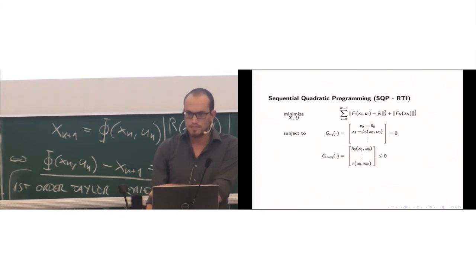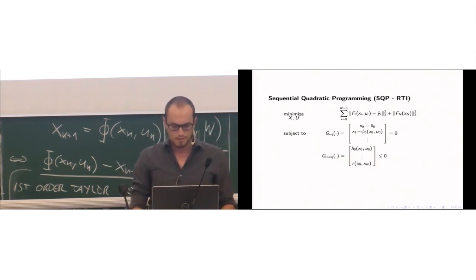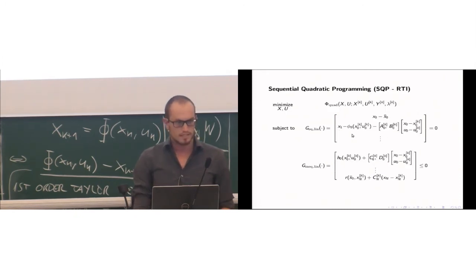Now we have a non-linear optimization problem, but we still have to somehow solve that online. For that, we of course use the RTI scheme, as I already said a couple of times. So it's sequential quadratic programming. This is still the NLP, with these non-linear constraints that you linearized this morning as well. We do exactly that. We sometimes even use RK4 with similar sensitivity propagation as you did, so that we get this quadratic approximation of our problem, which at each time step we solve as one QP like this, with the initial value embedding. So we get the nice properties of RTI, that it predicts the next solution based on the change in the parameter. As I said, this is the task of the integrator: you do a simulation as well as a propagation of the derivatives, such that you get this AK, BK.